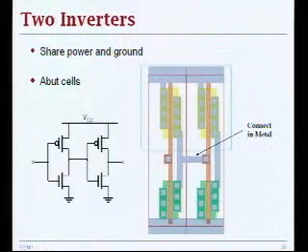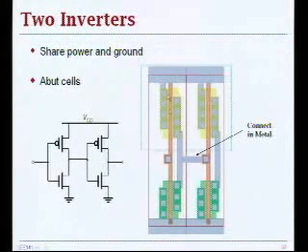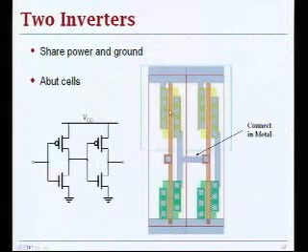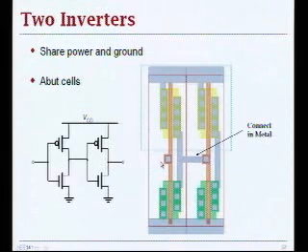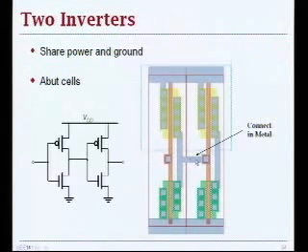So now if you have 2 inverters, it's a good idea to build a layout for one and just put them next to each other. In order to do so, you keep in mind the interfacing between different circuits. It's always good practice, if you can, for this kind of circuit, to put your input and output terminals at the relative vertical position. So when you put these two devices next to each other, all you need to do is put a straight line. You don't need to jog around, and you can easily abut cells and connect them to each other.